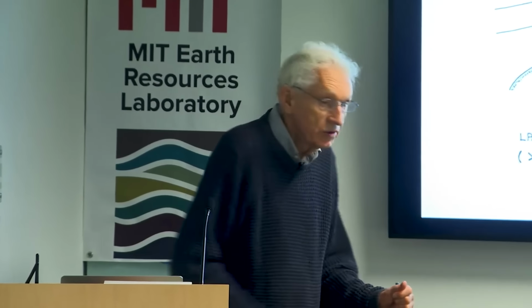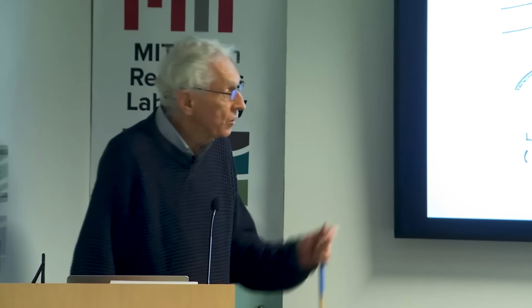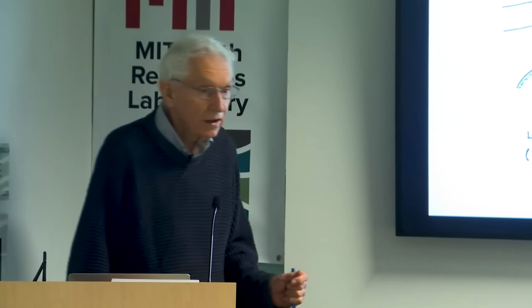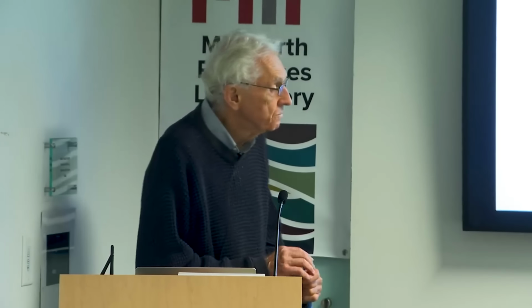And this is relevant to, if we're looking at a bed of silt or fine sand at relatively slow flows, that would be the first case. If we're looking at coarser sediment, like medium to coarse sand up in the gravel range, and strong flows with large Reynolds numbers, we'd be more like this. You get a lot of lift, which is important. We'll see that as time goes on. All right, that's my pitch on oscillatory flow.